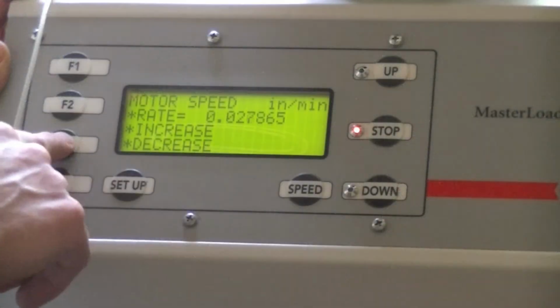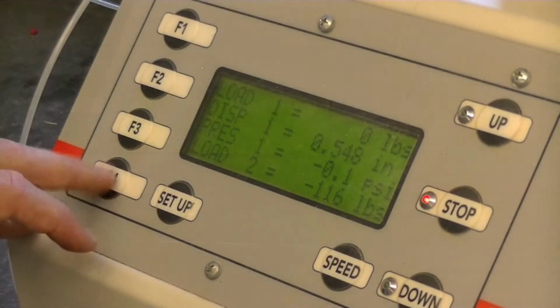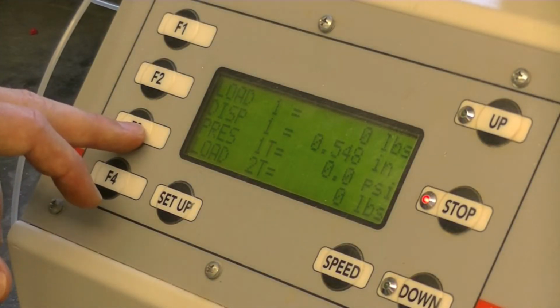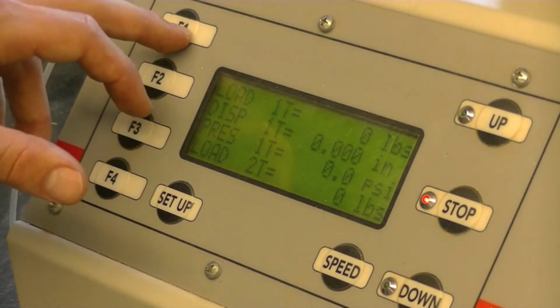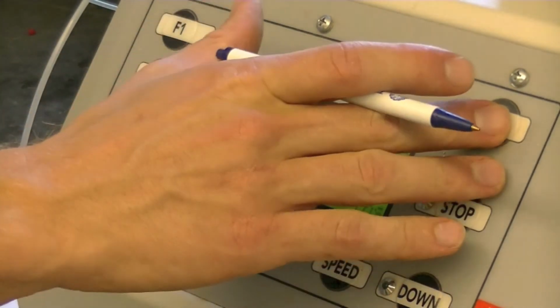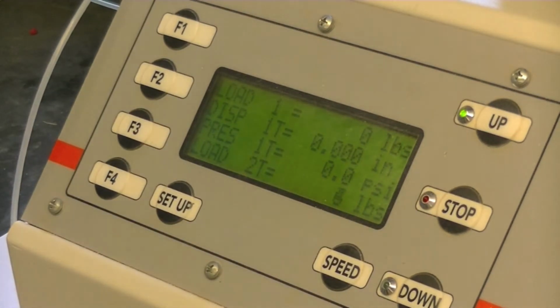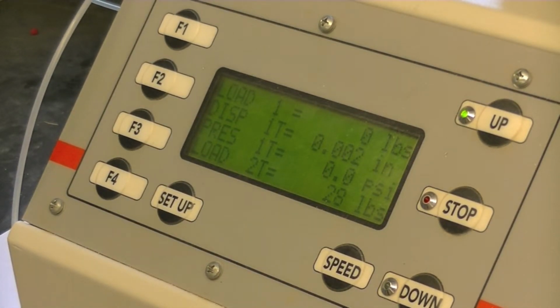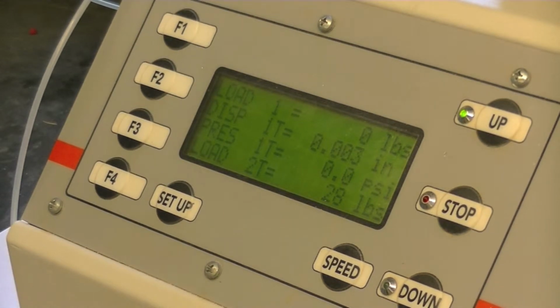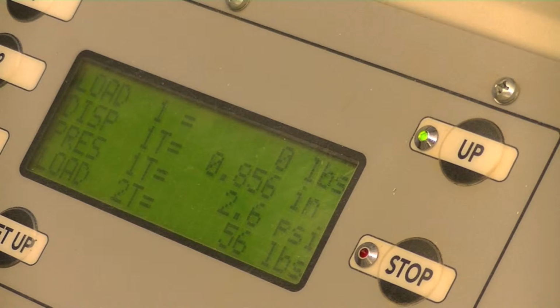Set the loading rate to 0.5% strain per minute. Tare the transducer and LVDT to 0. Prepare to record load, axial deformation, and pore water pressure as the master loader moves the specimen upward. Push the up arrow to start the test and begin recording in an incremental fashion. Run the test until failure or 15% strain occurs.